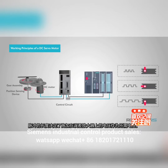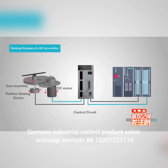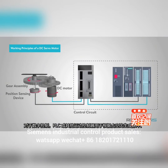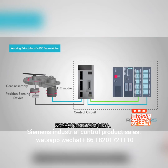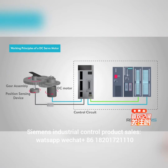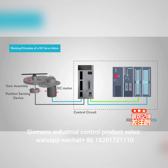The length of the pulse decides the voltage applied at the error amplifier as a desired voltage to produce the desired speed or position. For digital control, a PLC or other motion controller is used for generating the pulses in terms of duty cycles to produce more accurate control. The feedback signal sensor is normally a potentiometer that produces a voltage corresponding to the absolute angle of the motor shaft through the gear mechanism.